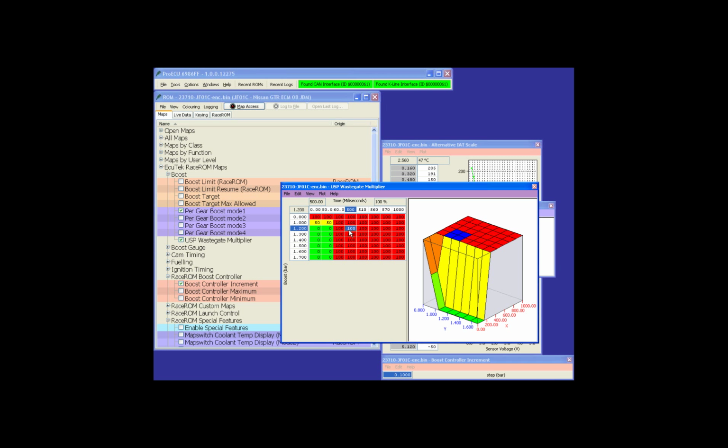So first of all, you want to maintain turbo speed during the gear shift. You want to try and maintain boost pressure primarily. There will be a slight drop. You can profile this map to maintain the boost as smoothly as possible, and afterwards, if you do get a drop in pressure and then an overshoot, you can use the time periods to dial in this map to set it up. You know, spend the time, understand it. It can give you perfect boost control on gear shift no matter how big your turbos are.